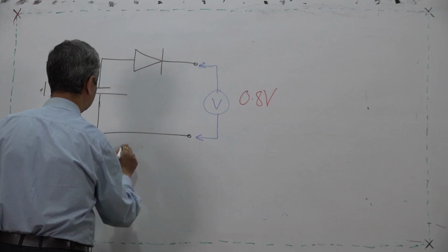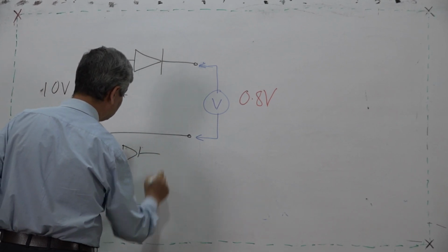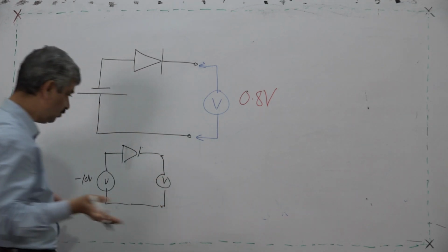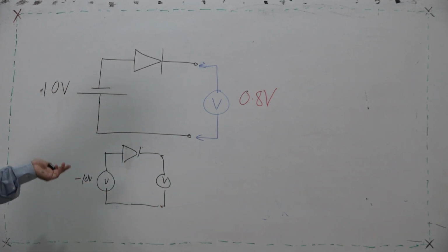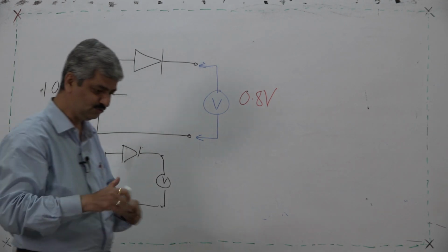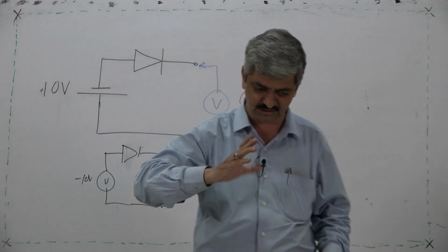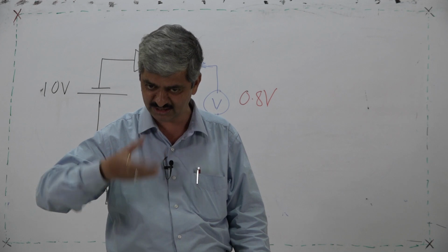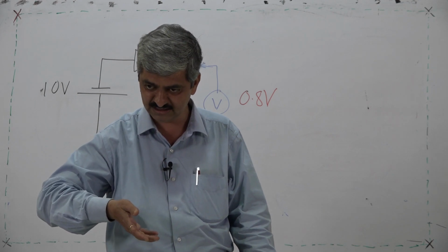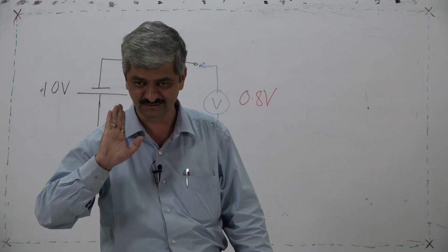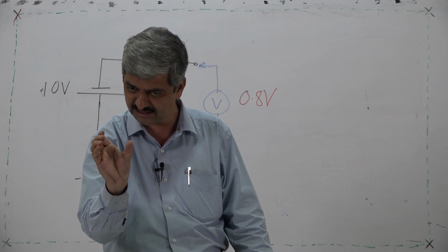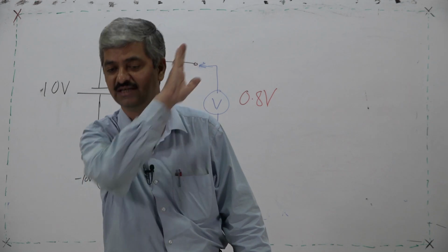And like this. Then there is a big question, and many will be confused here; most will answer 0, because it is reverse binary blocks. So, what is the wrong notion? In forward bias it eats 0.7, in reverse bias it blocks all or eats all. So the diode is seen as something which eats up 0.7 in forward bias and eats all in reverse bias, which is not the case at all.